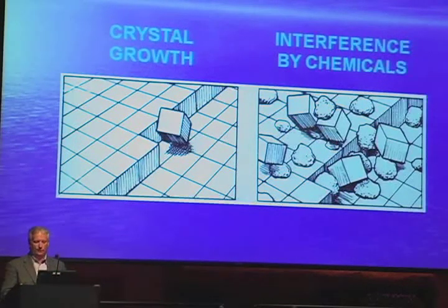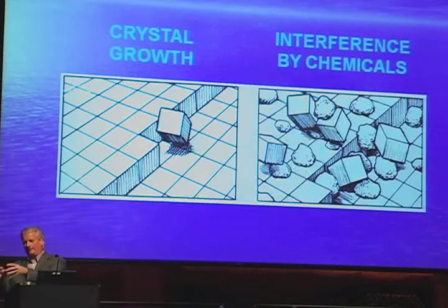What the phosphonates do is they actually modify that scale. So as calcium and carbonate come together, the phosphonates get their finger in there, basically, and they modify that crystal. So now it's not an organized crystal anymore. So it's trying to find a slot for itself. Can't find a slot. Can't find a slot. Eventually gets purged out of the blowdown. So it's basically a crystal modifier is what we do.